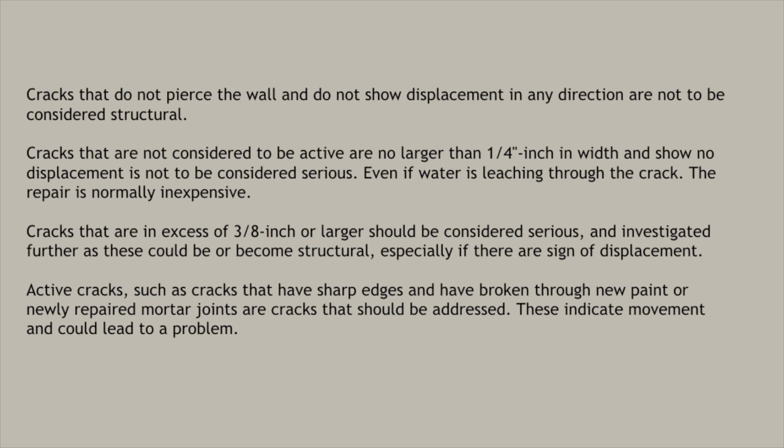Cracks that are in excess of 3/8 of an inch or larger should be considered serious and investigated further, as these could be or become structural, especially if there are signs of displacement. And active cracks, such as cracks that have sharp edges and have broken through new paint or newly repaired mortar joints, are cracks that should be addressed. These indicate movement and could lead to a problem.